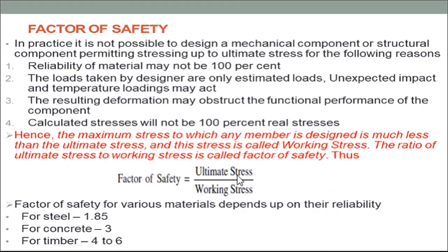Factor of safety. In practice, it is not possible to design a mechanical or structural component permitting stresses up to the ultimate stress, for the following reasons. At the time of designing, we cannot directly take the ultimate stress, because whenever we calculate the ultimate stress, the reliability of the material may not be 100%.